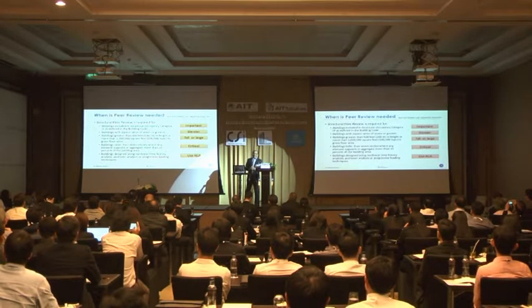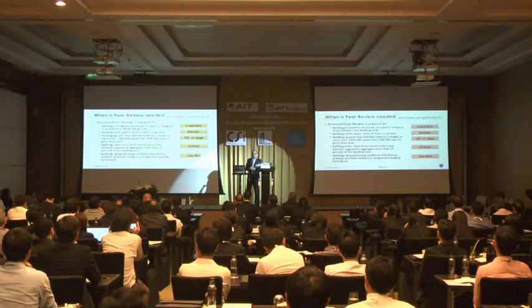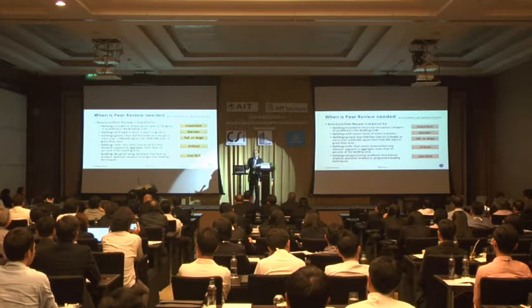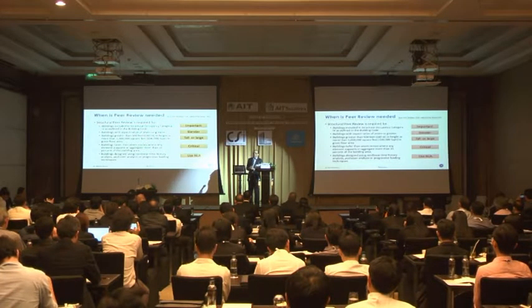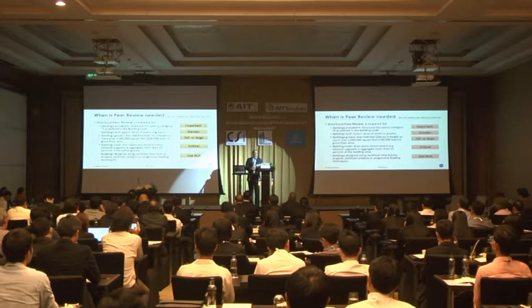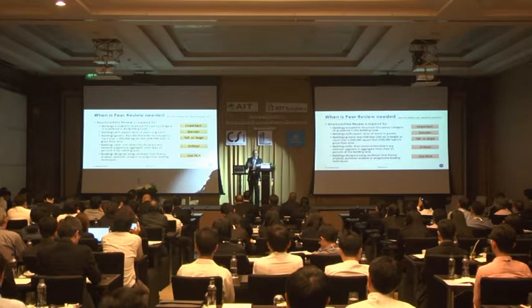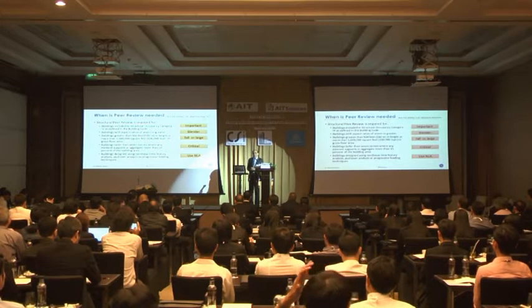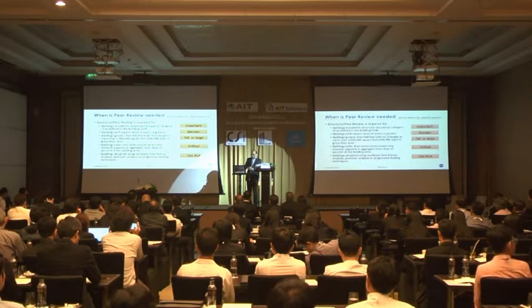Number one, important buildings. Number two, slender buildings. Tall or large buildings. Buildings that have critical members. Or analysis that uses nonlinear analysis techniques. So if any of these things are present in the building, then New York and many cities in the US require that a third-party review be carried out for the design. You can see that many of the buildings in Bangkok or in the Philippines will actually qualify based on this requirement, and the peer reviewer should be engaged by the clients or the developers to ensure that things are going well.